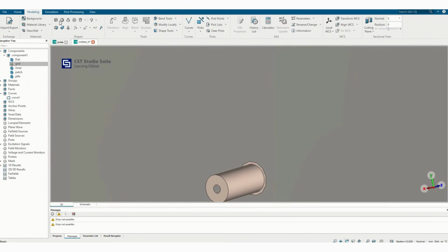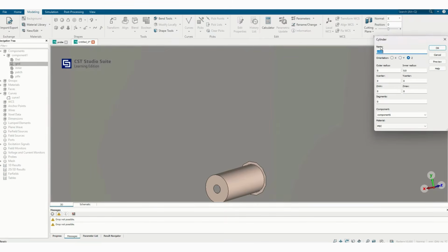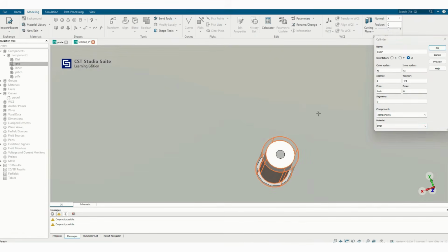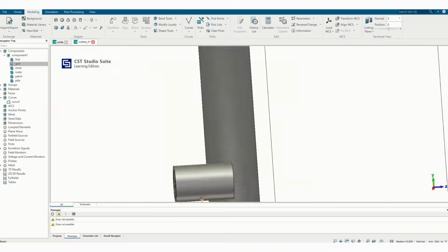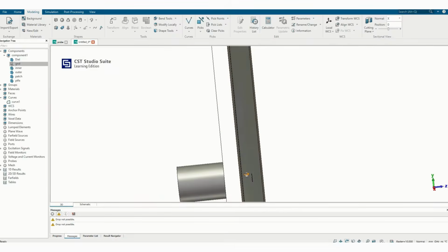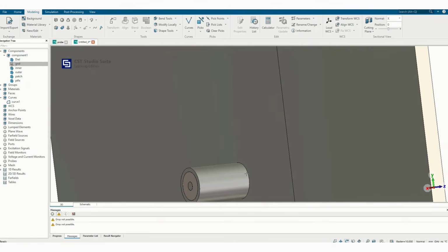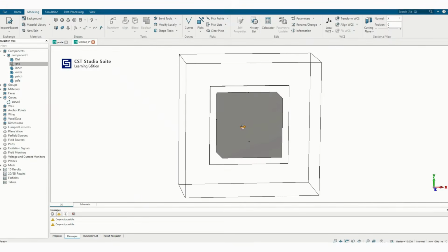So now our aim is to provide the outer conductor. So it has a radius from R2 to R3. Y center is minus L by 4. Z minimum is from H min to 0. So this is PEC. So now we can see that it is getting connected to the ground plane. So the inner conductor is shorted to the top patch and outer conductor is connected to the ground plane. So I think everything is ready.